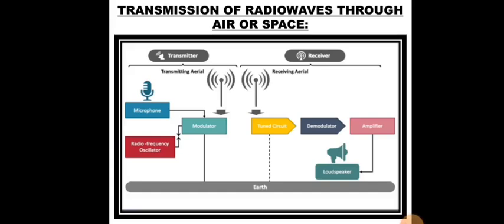Now, a communication satellite is in fact a microwave relay station. It is used to link two or more ground-based microwave transmitters, known as earth stations or ground stations. The satellite receives transmissions on one frequency, uplink, amplifies or repeats the signal, and transmits it on another frequency, downlink.